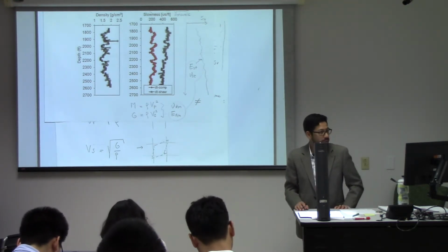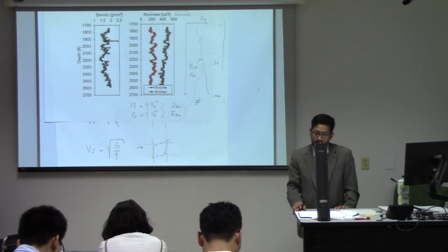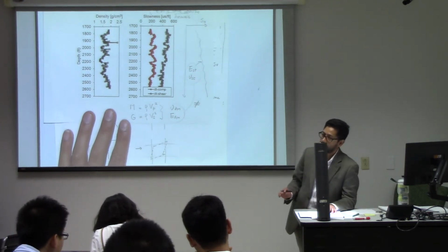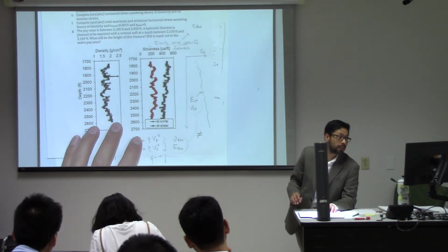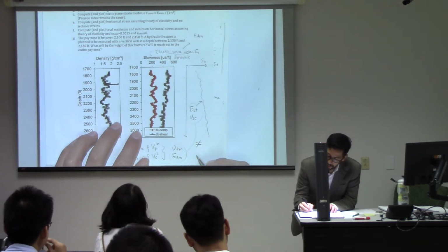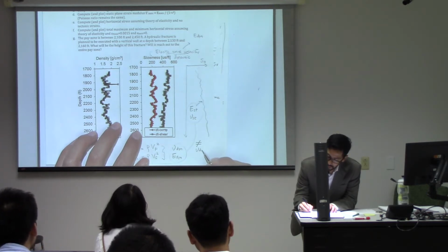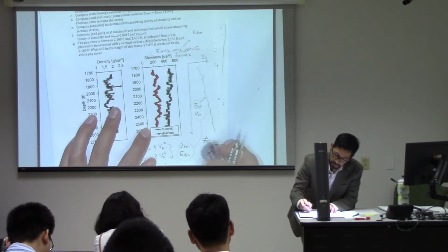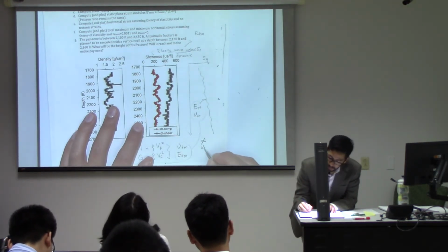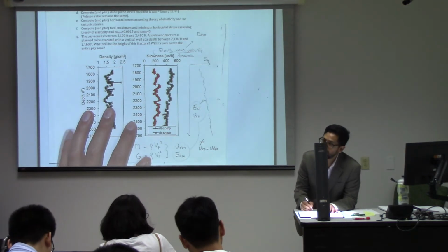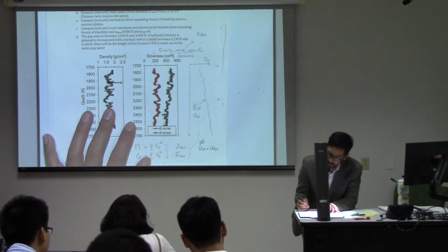But everything you have to know right now, for this simplified homework, and it's a simplified assumption, but many people use it a lot, especially in industry practice, is that our unknown is the static modulus. You're going to assume the Poisson ratio is the same, static or dynamic? Yes, we're going to do that. We're going to assume those are the same, which is a reasonable assumption for small strains.